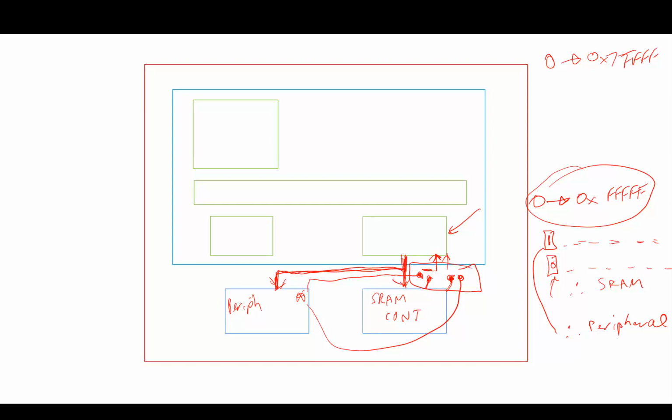Okay. Now the other thing to keep in mind, if you have this double the size of address space, that means the address bits are now 20. It is now 2 to the 20, so there are 20 bits. But these modules down here still only take an address input size of 19 for the Avalon bus side. So you need to convert that 20-bit address into a 19-bit address to feed into these modules. So I'll leave you to think about that.